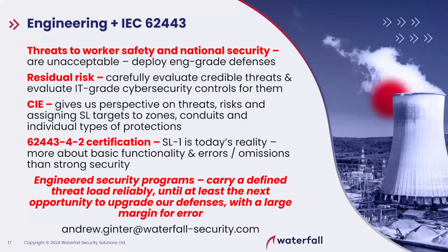There's nowhere in 62443 that says you can only connect from one network to the next network up. You cannot skip networks. You cannot punch a connection through 2 and 3 layers of firewall. There's nothing that says that, to my knowledge, in the 62443 standard. But this is best practice. It's considered best practice not to punch connections all the way through. I think Purdue still has a role to play. And what do you do about the industrial internet?